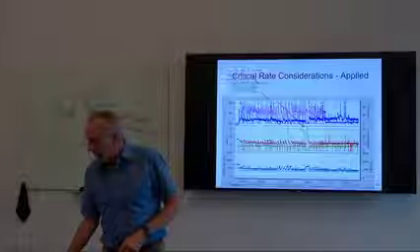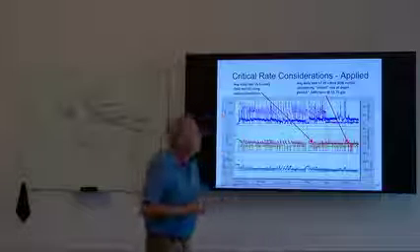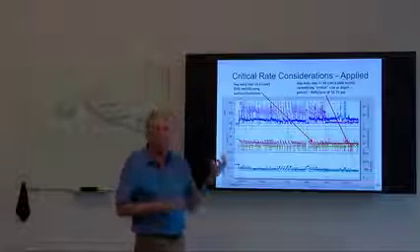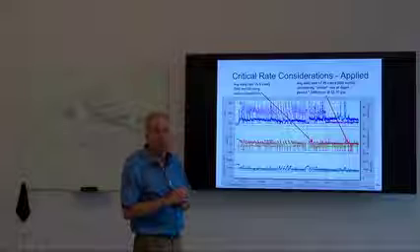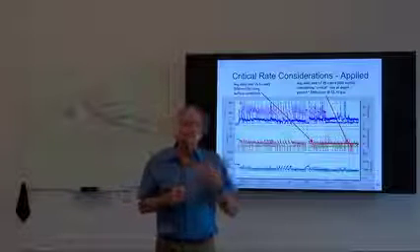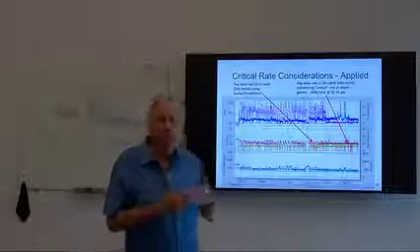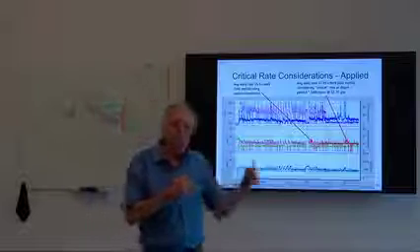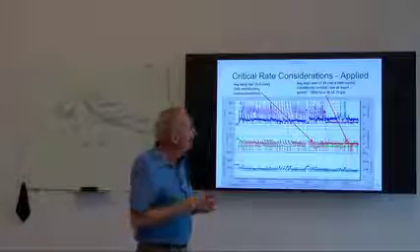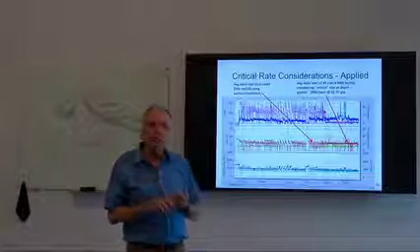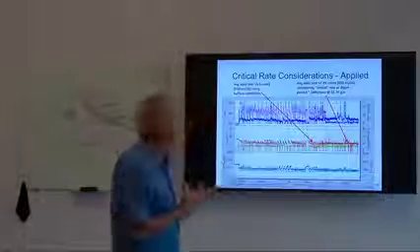And we had a case a number of years back with a customer in Canada who switched their philosophy from using surface to downhole predicted pressures in order to calculate their critical rates, which meant that they started shutting in sooner in afterflow. Plunger arrives at surface, we're into an afterflow period, and now we're trying to determine when do we shut the well in to return the plunger to bottom and cycle again. Well, we want to make sure that we have enough fluid for the next cycle. We want to make sure that we don't flow so long that we just accumulate lots of fluid.